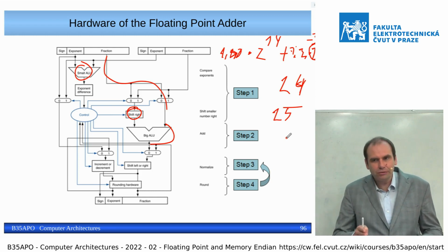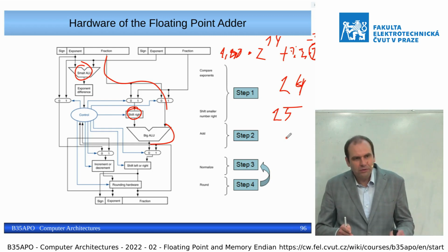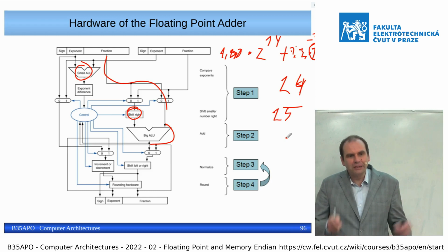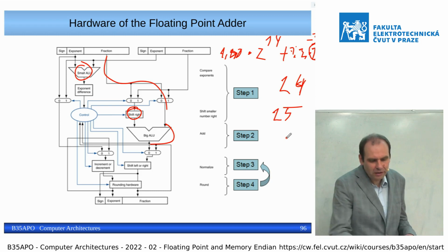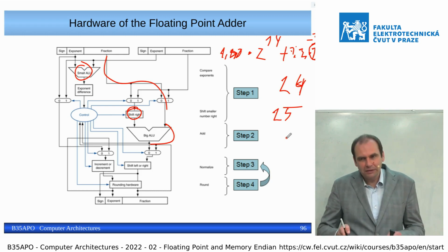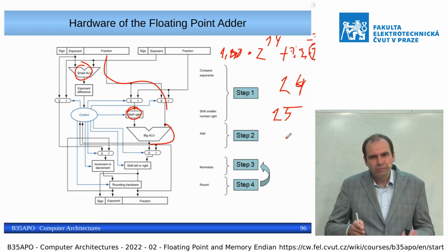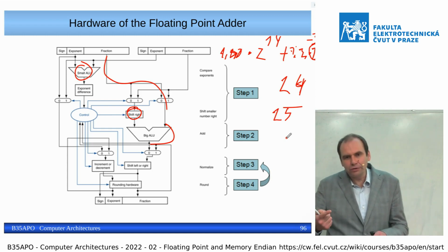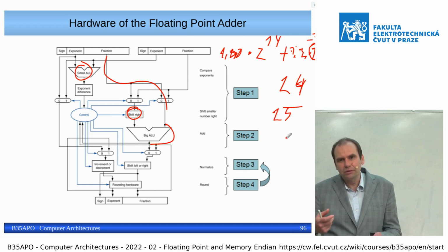And what does it mean to do with the exponent to have the same arithmetic value? What happens? We have a value which is bigger than 1, multiplied by the exponent of the bigger of the input numbers. We need to normalize it, so we need it to be smaller than 2. So we divide it by 2, but the arithmetic value should be kept the same. So for the exponent we need to subtract.